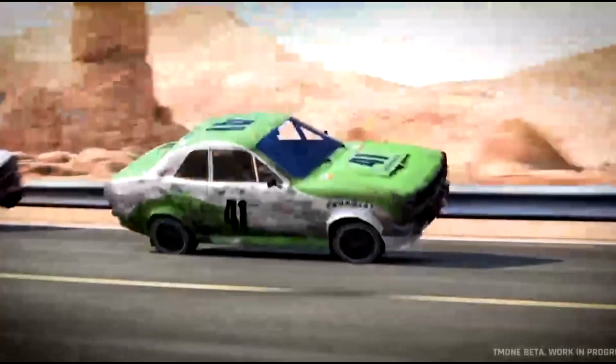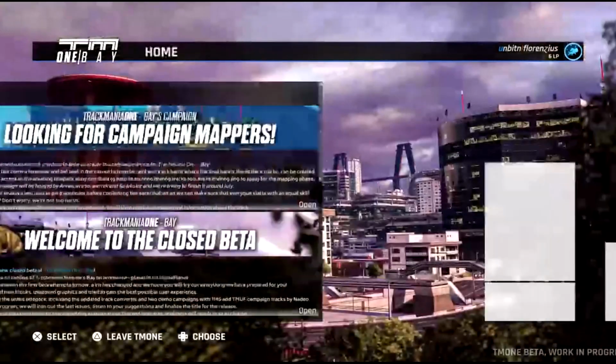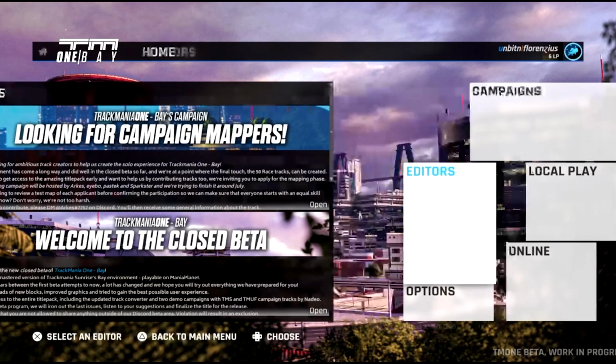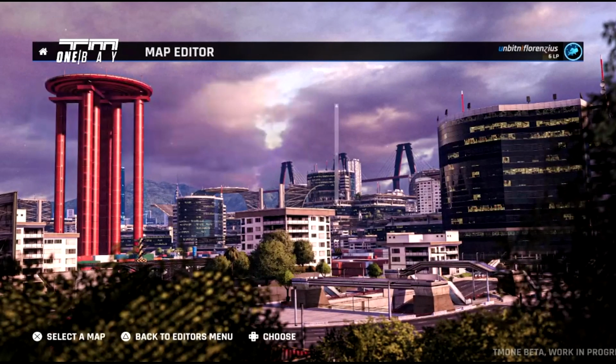That's something you need to figure out yourself. Using a margin of 0.01 is an option, but if your object is really big and you have many faces, then it may be a really big margin. And if you have a smaller object with 2 or 3 shells, then it might be too small. So we cannot say for sure.